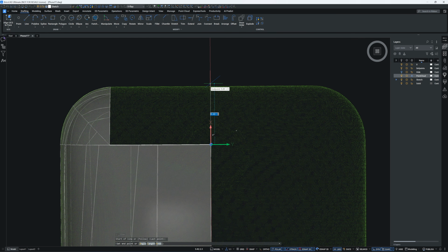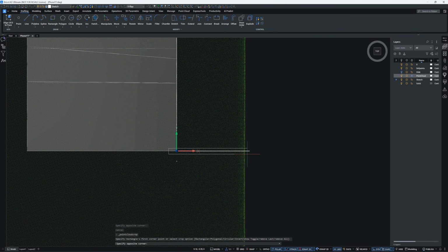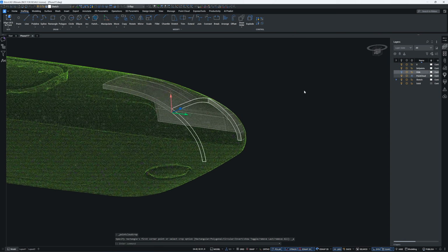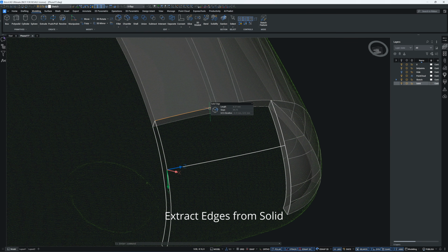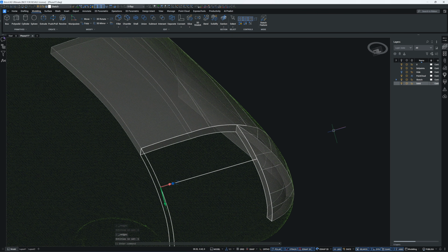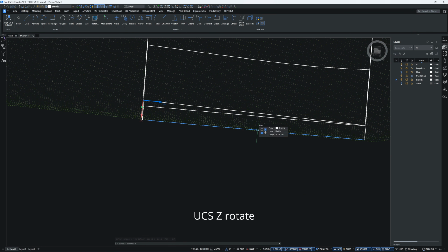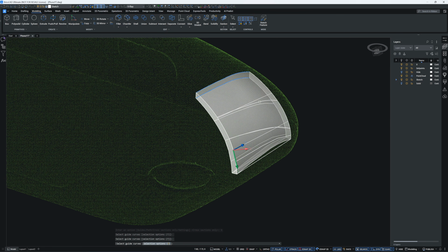Next, I'm creating the new loft section. This one runs perpendicular to the previous section and must connect seamlessly to it. I'm creating the sketch profile on the mirror plane, tracing the point cloud just like the other cross sections. Now I'm extracting the edges from the previous loft section to use as guide rails for the new one. By doing this, the new loft solid will join perfectly with the other section when you run the union command, giving you a very healthy solid model.